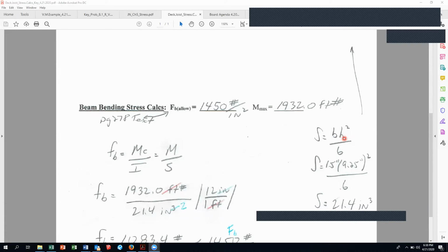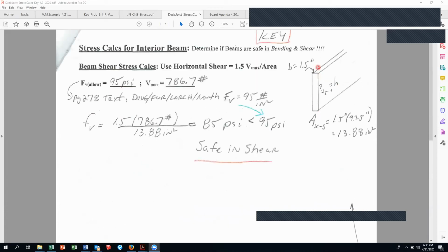And don't forget AutoCAD. AutoCAD gives you shape properties, right? If you had a shape that you showed in AutoCAD, you can get the cross-sectional area. It also gives you the moment of inertia, the section modulus. Another one is called radius of gyration. Pass the word. You might want to remember that one. Radius of gyration is on the units handout, I believe page 2, and it deals with buckling in columns.